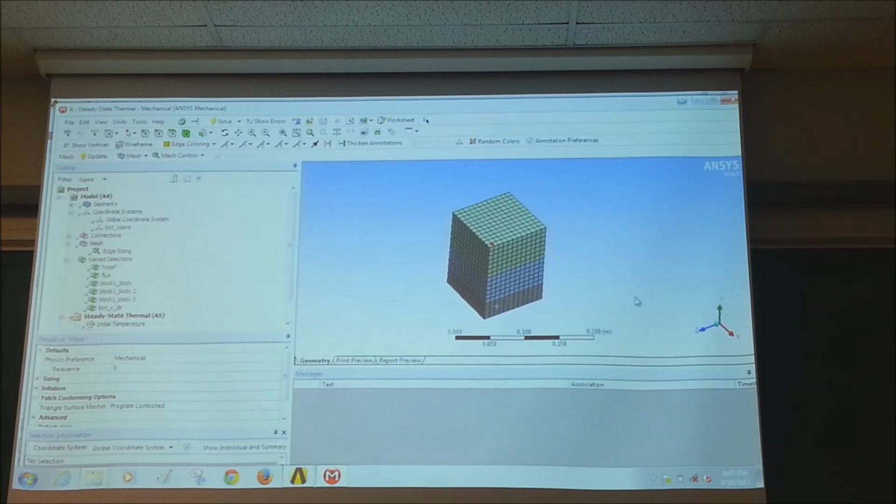You can do so many things with it when you do this kind of stuff, right? Name selection. I mean, there are tons of things you can do. You can control, especially when you have a complex geometry. If you don't use name selections, you're absolutely not using Ansys the way you should. So you should absolutely do that. So now we got this name selection.